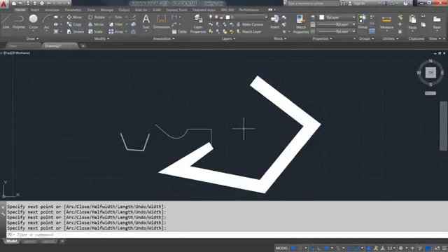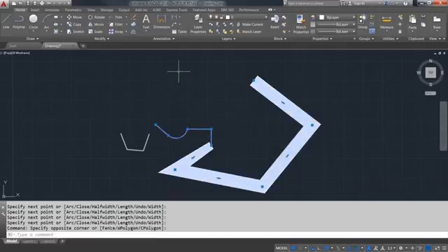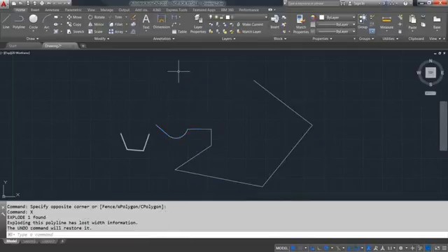So let's end that. Now one thing that I noticed that's interesting is when you explode a polyline that has width, so let's just do that real quick. We'll use X for explode. You can also obtain this on the Modify ribbon tab at the top. All the resultant lines and arcs and various pieces of the former polyline now don't have any thickness any longer.